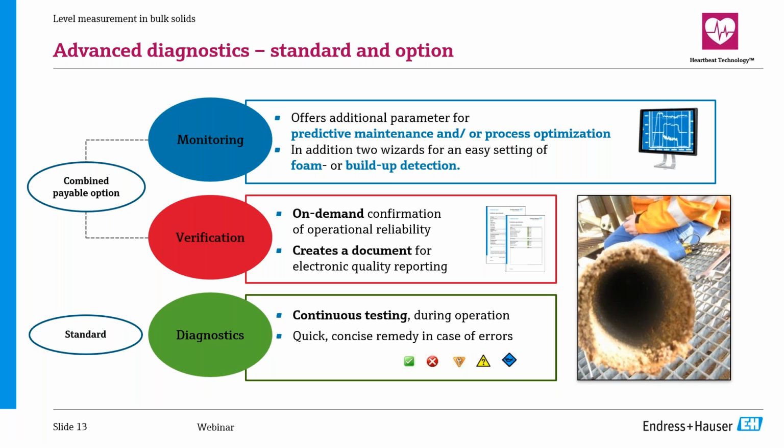Now that we talked a little bit more about dusty environments, let's talk about the importance of advanced diagnostics. So why is it so important? You can see on the picture a free space antenna with a strong build-up. In general, free space radars will work normally until the build-up reaches a point where the measuring pulse is nearly totally absorbed on the antenna, and nearly nothing goes to the process. So this is the point where your instrument will stop working. And this is where the advanced diagnostics really help us.